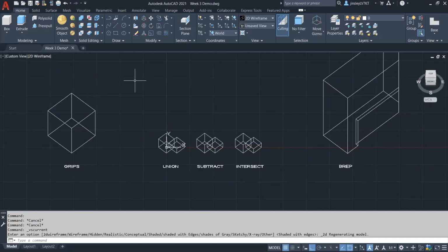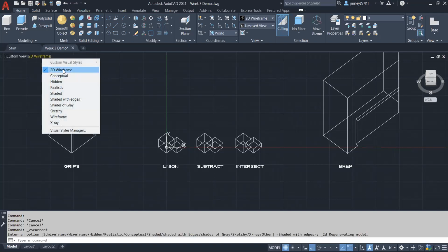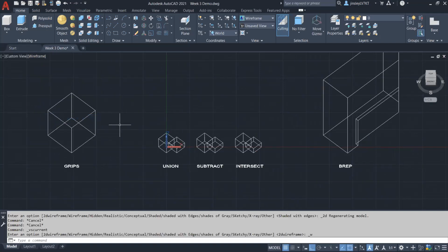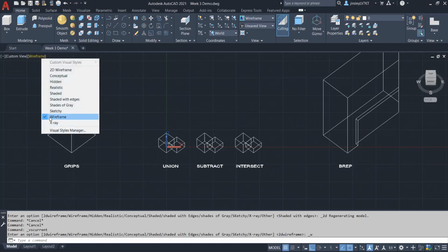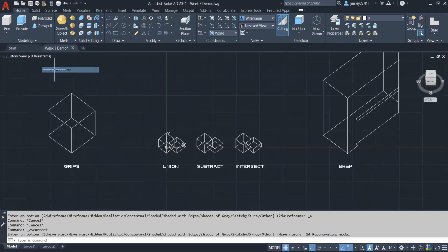And then when you reopen it, the way that we save our memory is by using our 2D wireframe views. Because right now, this is not rendering. It's just showing us the edges, right? So if you get a really complex file and it's not running smoothly, you can always switch to your 2D wireframe, okay? And there is a 3D one as well, I believe, this other wireframe, but it computes like crazy and I don't know why. So don't use the regular wireframe, always stick with the 2D one. It uses less memory and it's easier on your video card, right?